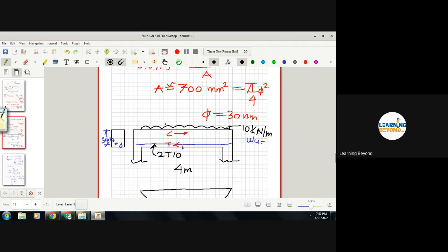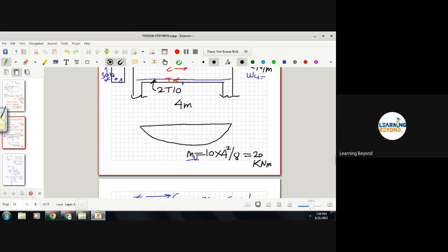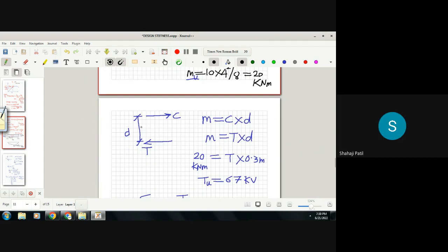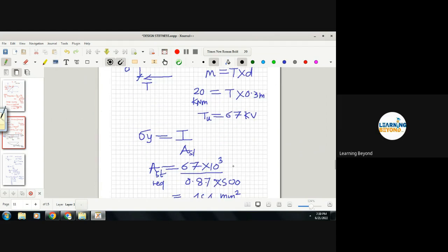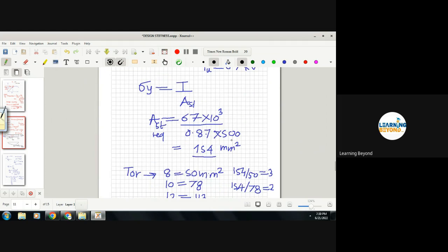But once you calculate the steel by those rigorous, detailed methods, or do the design by RCDC software or any software, you can quickly check like this. Just check the moment, divide the moment by lever arm D to get the tension, then use the permissible stress and you will get the area quickly. It takes hardly 2-3 minutes to get the AST required. Whatever steel design is done by RCDC software or an Excel program, you can quickly check whether it is right or wrong.